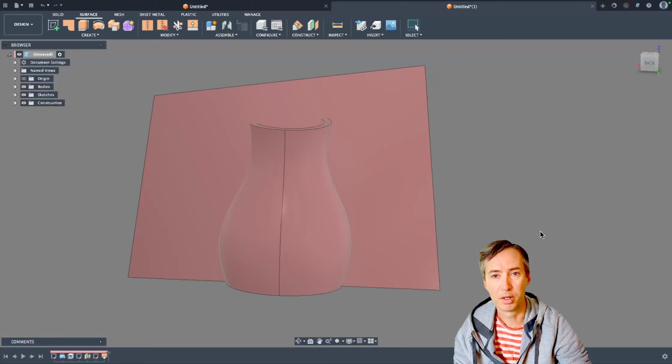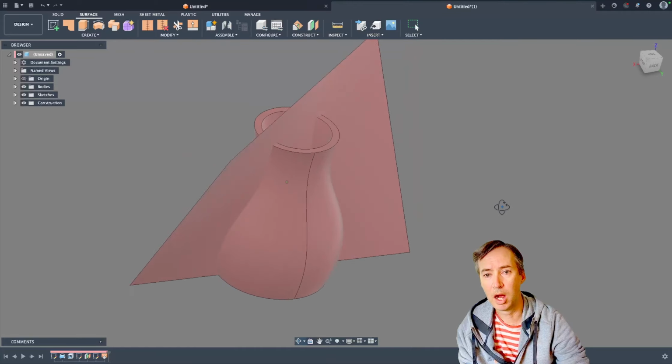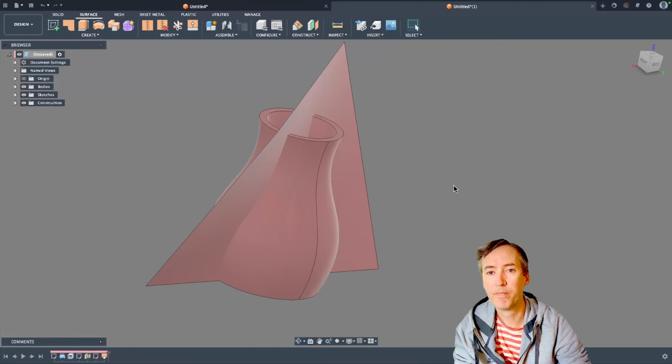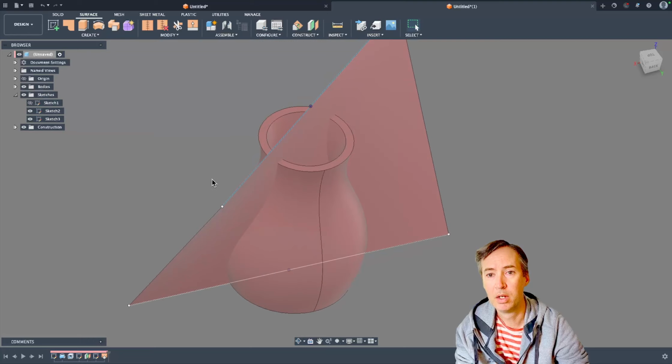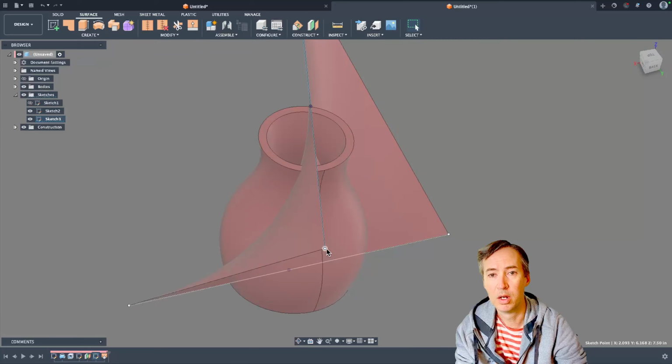And then I'll click OK there. So this is how I'm going to get that swirly line kind of thing going. If I go back and look at my sketches, when I lofted, it turned off the visibility of these sketches. So I can still drag this top sketch around to get this loft to twist a little bit more.